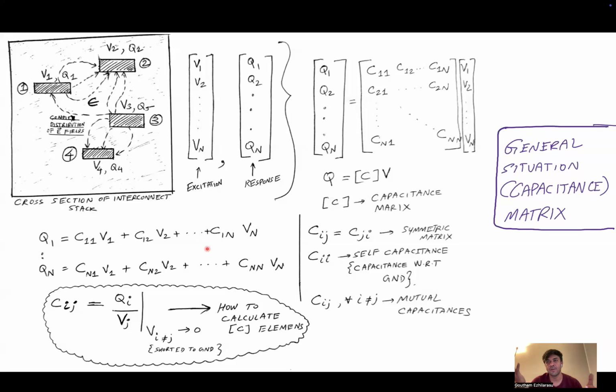So generally, if you go to a PCB, what you usually do is you have layers of conductors separated by a ground and voltage plane. And as we will see in a couple of slides later, those voltage planes actually shield the interconnects from one level to the other. So the interconnects on one level do not affect the interconnects on the second level, and so on. So that's another way we can reduce this cross coupling, right?